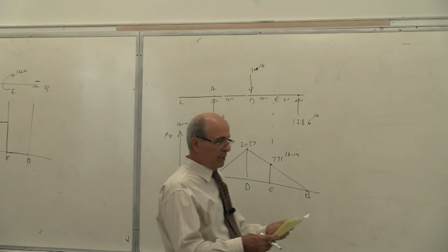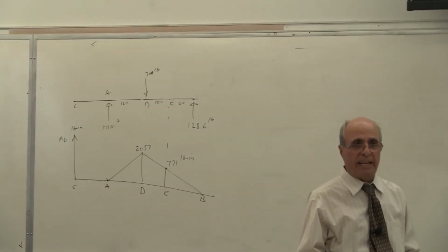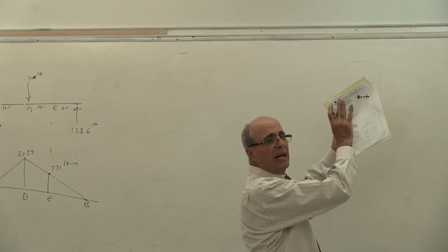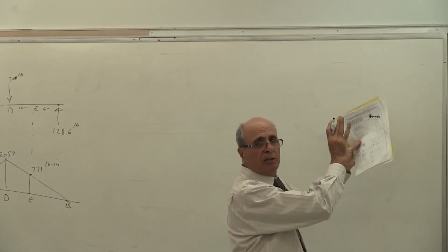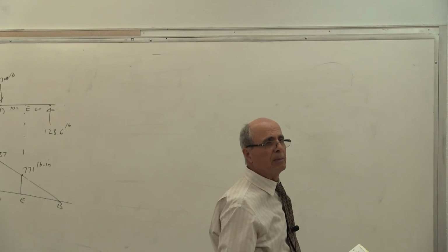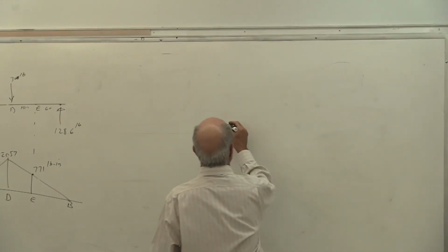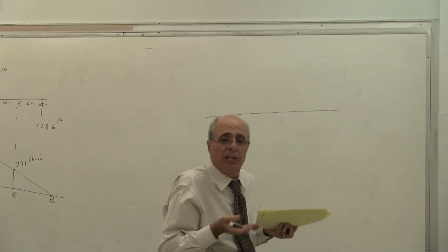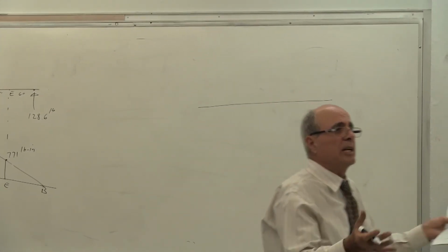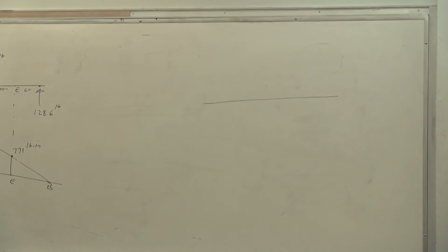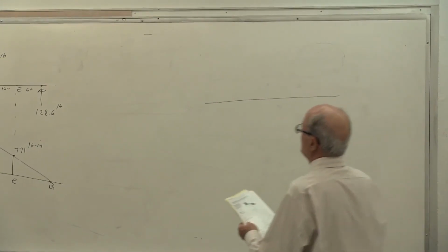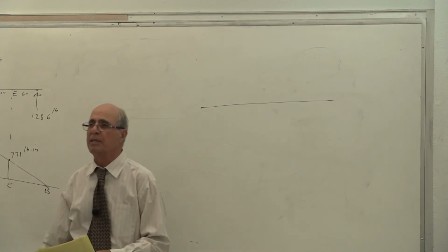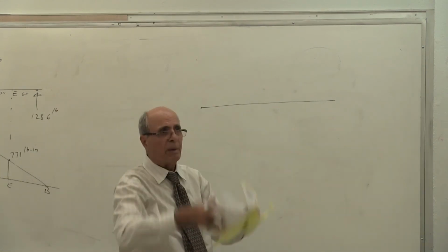So, okay, the next one is the moment about the y-axis. Again, you can draw that horizontally or you can draw it vertically, depends on how you feel comfortable about it. So let's do it vertically, but don't forget, I'm showing it vertically, but actually it is the horizontal plane, therefore it's moment about the y-axis. Is that correct or not? Therefore, you put those points again. The same, actually, you draw this underneath each other. It's much simpler. So draw all of them, draw parallel lines.